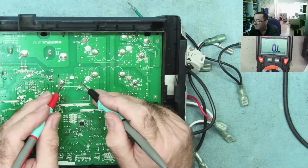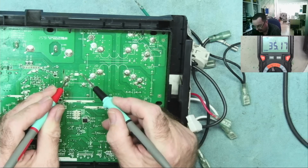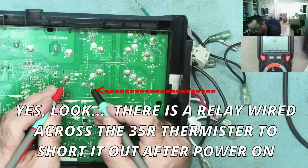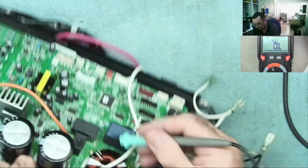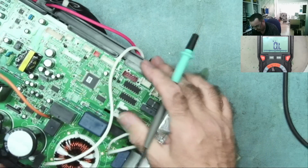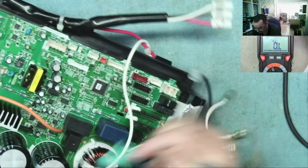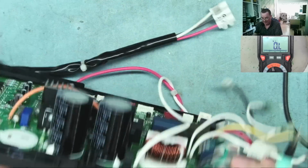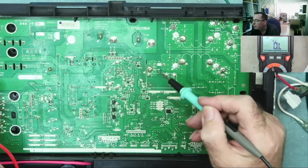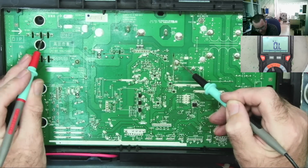This then goes through a resistor here, which is actually 35 ohms. That could be a thermistor, it's marked as R1. It's this thing here, so it's a bit hard to say what that actually is. Okay, but that's where it goes through there. Then you can see an orange wire which goes over towards these bridge rectifiers, which is marked orange. So this goes up to the bridge rectifier on one of the AC inputs.